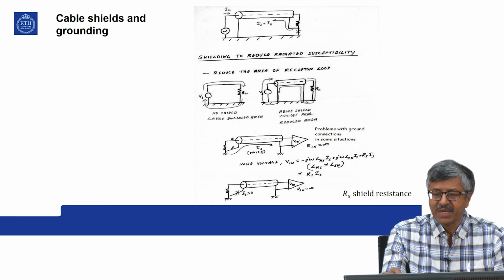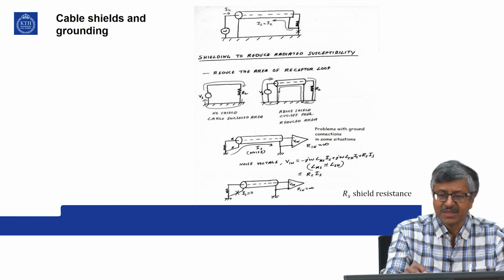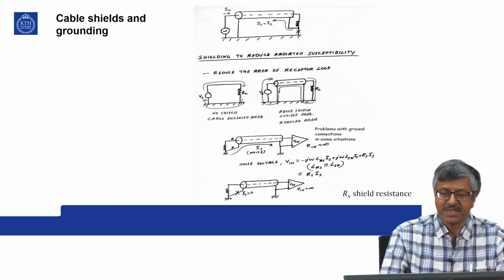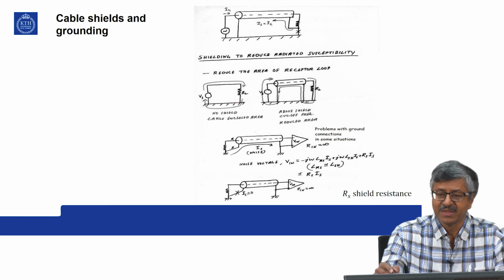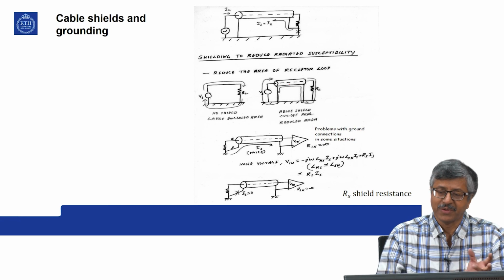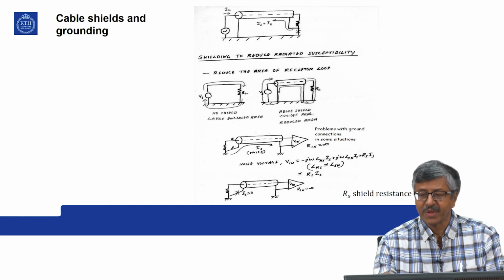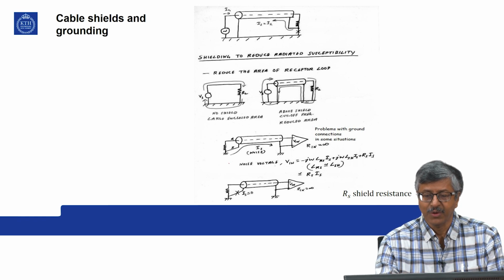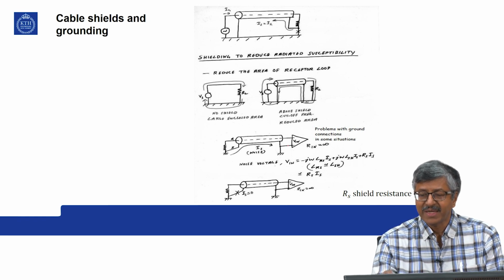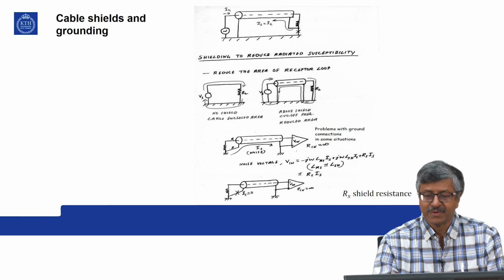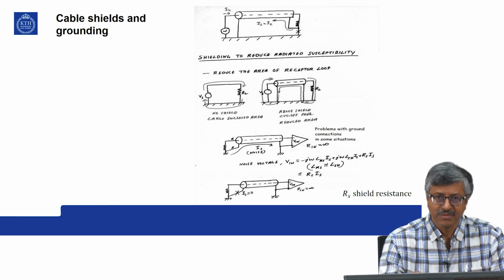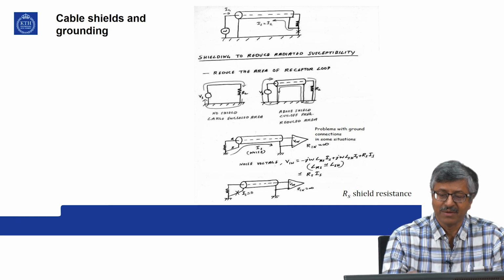above shield cutoff frequency. So, you can say that this is a very large area being presented for external fields. Now, you are presenting very small area. So, that way also you can see it. But sometimes if you have connection at both ends, it can create some problems. So, you cannot do connections mechanically, without thinking on both sides.